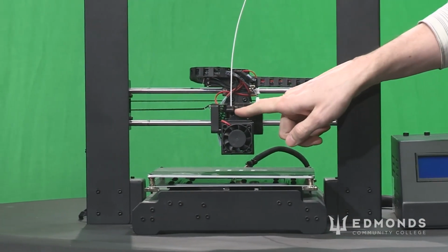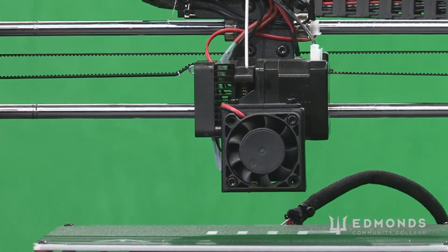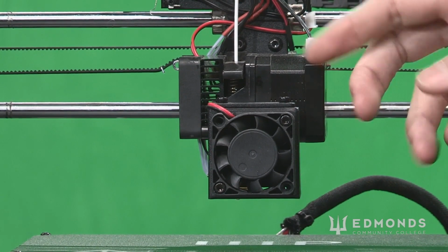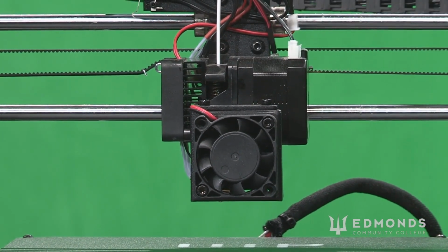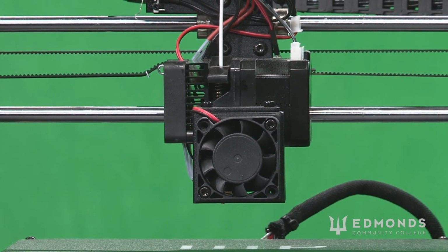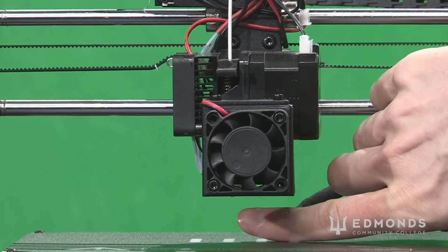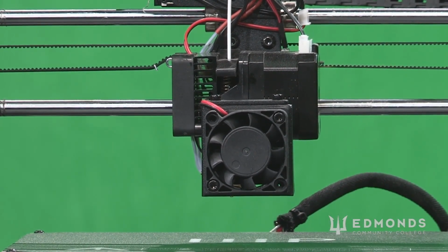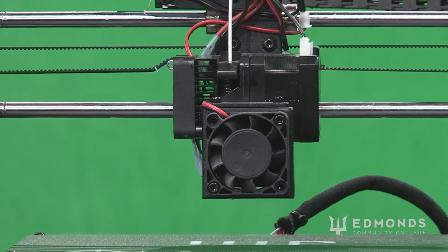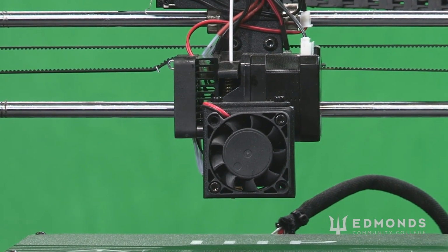So our extruder here essentially acts as an advanced hot glue gun. It runs at generally a much higher temperature, and it's pulling in material using a motor here that turns a feeder gear, so we have a control for the rate. However, other than that, it's not really that much different than a hot glue gun or some other simple extruder. The extruder tip underneath can be made of a number of different materials. Brass is generally a cheap and effective option for that. However, if you want a more durable tip, titanium carbide would be a good choice.